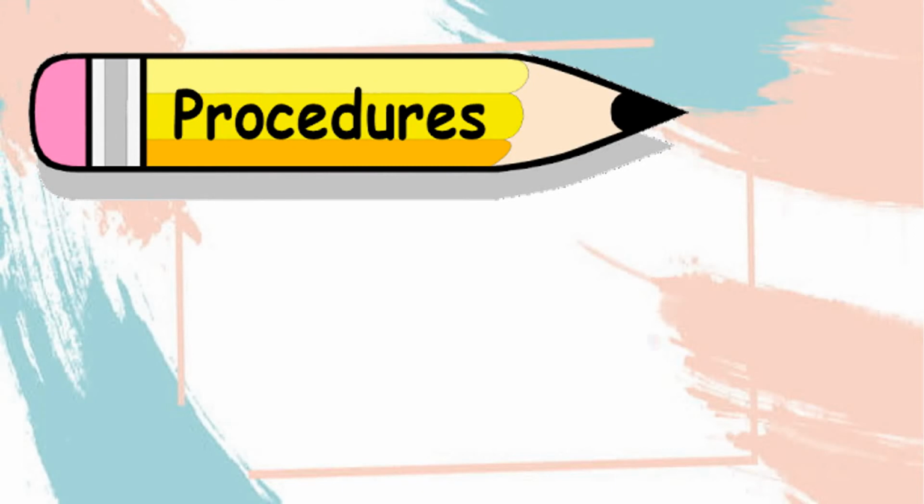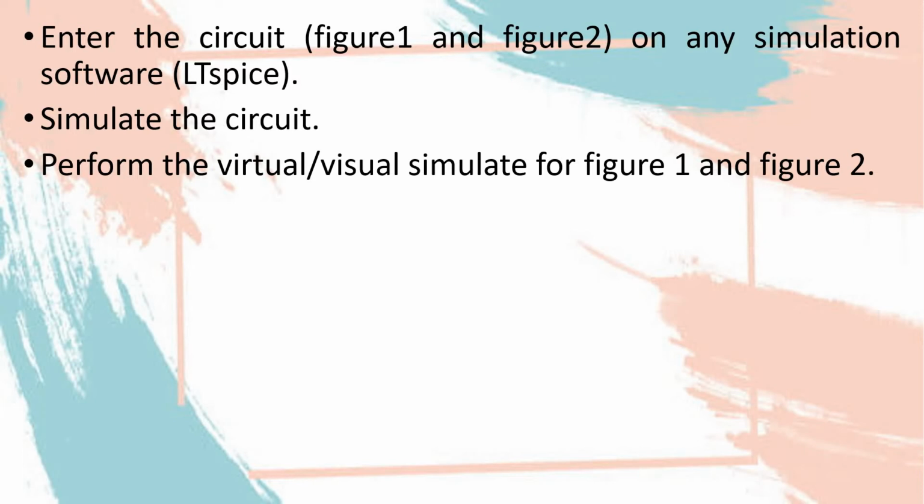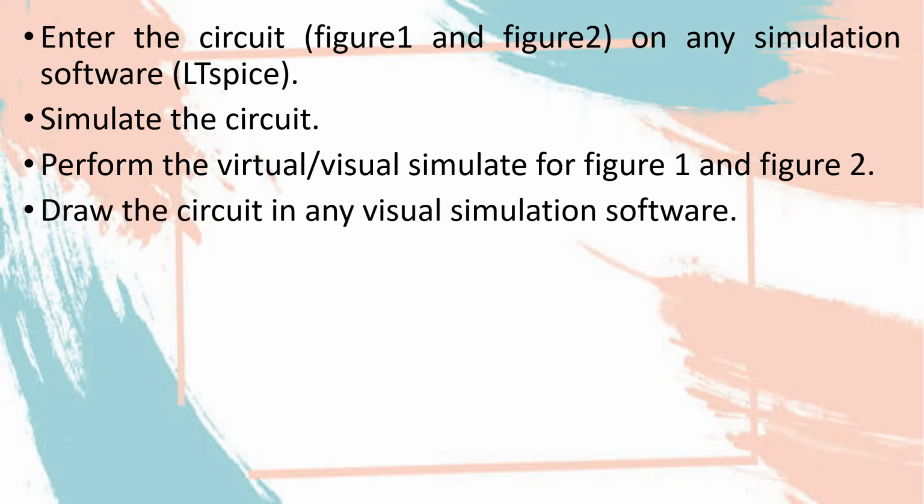Okay, the procedures. Enter the circuit figure 1 and figure 2 on any simulation software. We are using LTspice. Simulate the circuit. Perform the virtual simulation for figure 1 and figure 2.